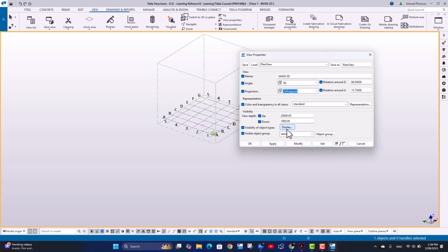As an example, for a famous case, if we are working with a mezzanine floor and we have got a bracing below this mezzanine floor, or a roof, for example, and we are working on a bracing on it, the bracing is usually placed lower than the beams, the secondary beams. If I set a view depth lower than this, I wouldn't see the bracing.